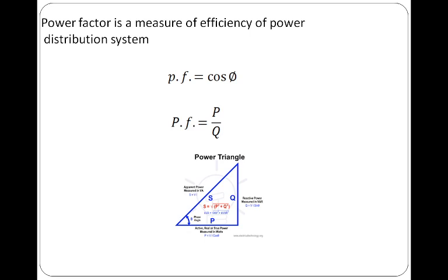Power factor is usually stated as leading or lagging to show the sign of the phase angle, where leading indicates a negative sign and lagging indicates a positive sign. A purely capacitive circuit causes reactive power with the current waveform leading the voltage waveform by 90 degrees, while a purely inductive circuit causes reactive power with the current waveform lagging the voltage waveform by 90 degrees.